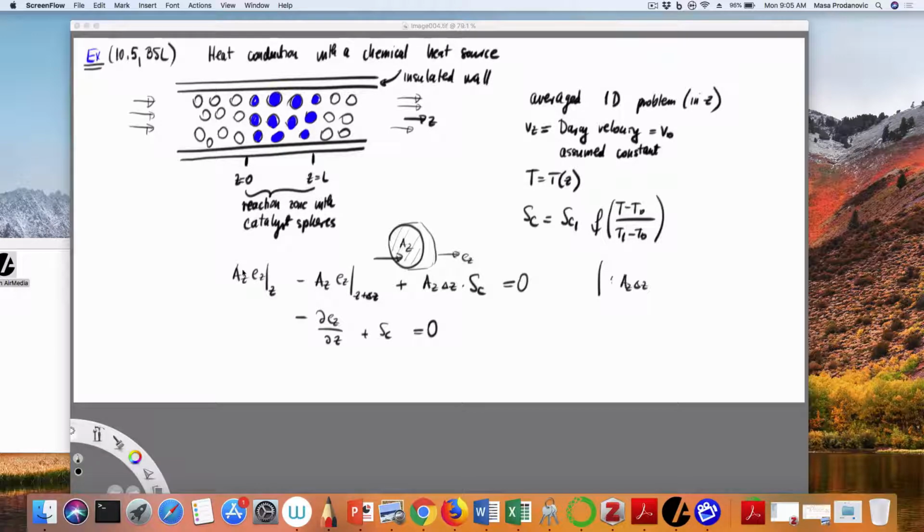So what I do then to balance is imagine my little tube, even though this is a 1D problem and I could have just drawn a line. Volumetrically I do have some area of the tube times the combined heat transport, or flux vector, that comes in on this side minus what comes out at the other side.